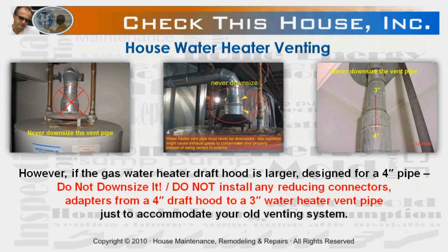However, if the gas water heater draft hood is larger, designed for a 4-inch diameter vent pipe, do not downsize it. Do not install any reducing connectors or adapters from a 4-inch draft hood to a 3-inch vent pipe just to accommodate your old venting system. Downsizing will prevent exhaust gases from discharging properly through the vent pipe and instead might partially or even completely direct them into your house.